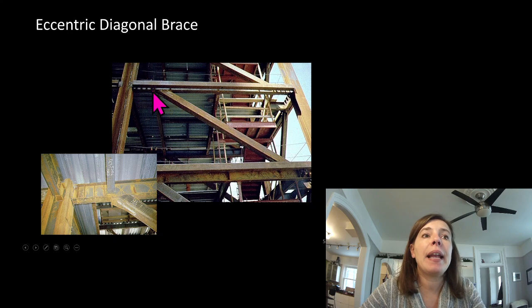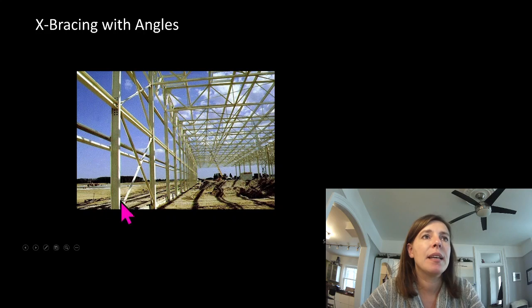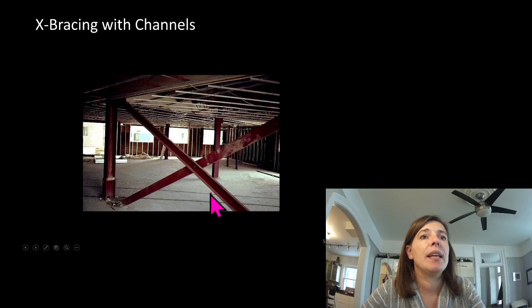This might have been about capacity design, but I doubt it. Most likely, they needed a door right here, so they have an eccentric diagonal brace. Angles, definitely tension only, because these buckle so easily. Channels, probably also tension only.